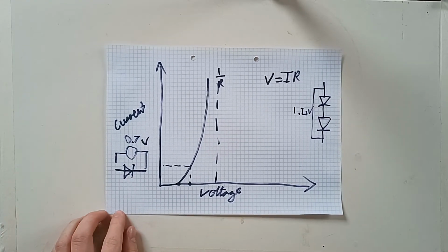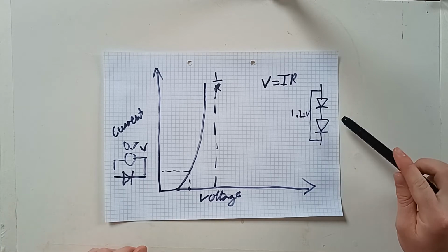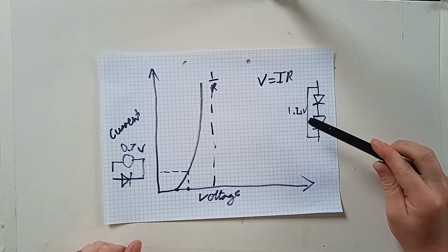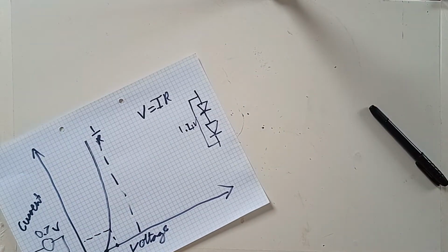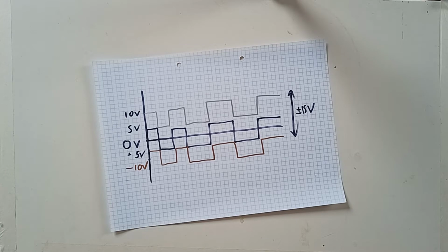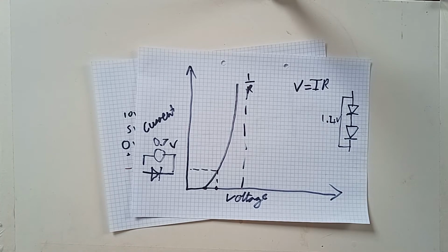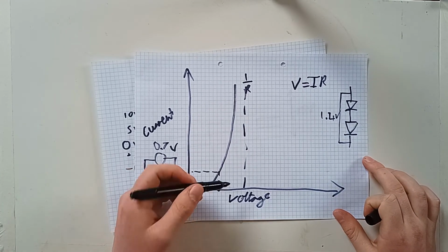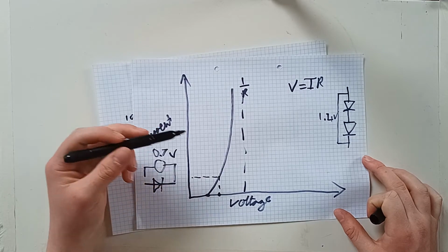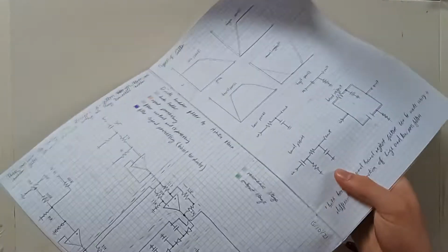So by adding more diodes, which increases the order of the filter, you are then also requiring a larger bias voltage. And if you make it so you can adjust the bias voltage, so the width between these 2 points here, you can then change the effective resistance of your diodes as I'd shown on this graph. Because you're changing the voltage across the diodes, you're getting a different point on this curve, allowing your filter to have different cutoff points. And that's exactly what this circuit here does.